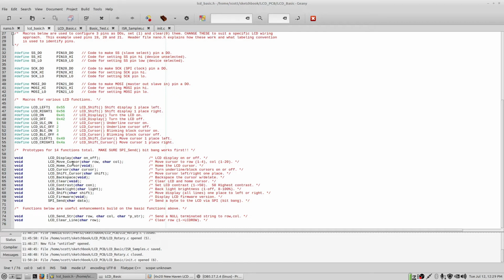And all the videos that you see with the LCD run from this SPI bit bang send function at 25 kilohertz. The display updates pretty much instantly, so there's no perceivable delays or problems. So this should work out pretty well. It's been tested reasonably well too. So we've got the functions here. They're explained,